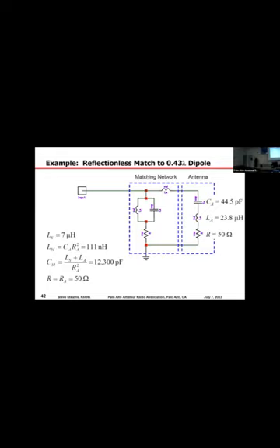When you're close to the design frequency, the resonant frequency of this thing, all the current goes through the antenna and none of it goes through this other resistor that's inside the network. As you shift off of the design frequency, less energy goes into the antenna's radiation resistance of 50 ohms, and instead it gets shunted into the second resistor that I've added. So all the energy that goes in goes somewhere, but it's a continuous, smooth variation from one resistor to the other resistor as you vary frequency.